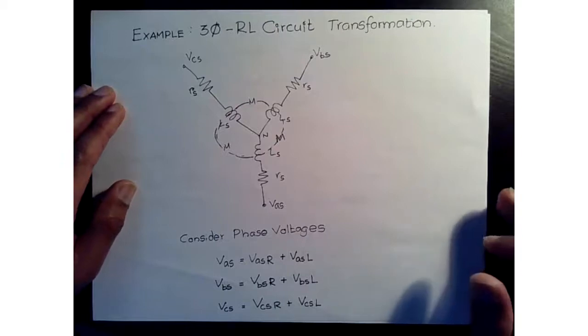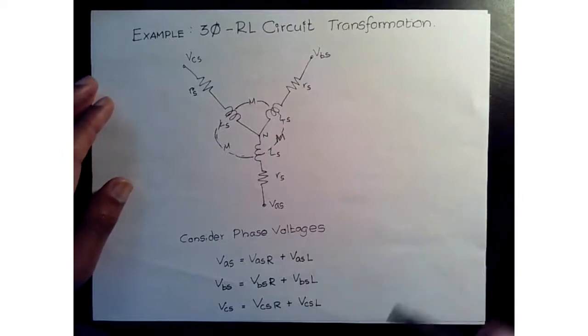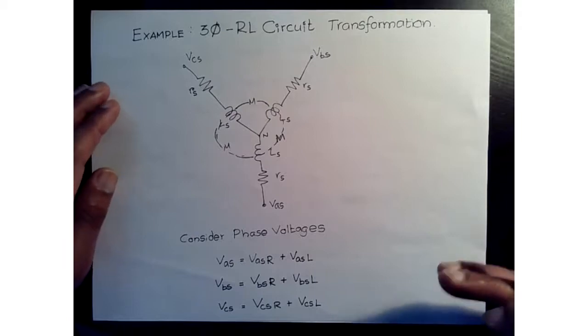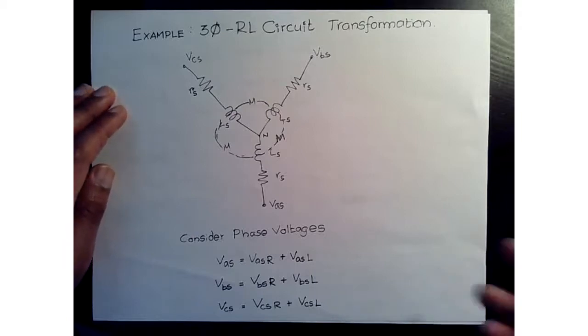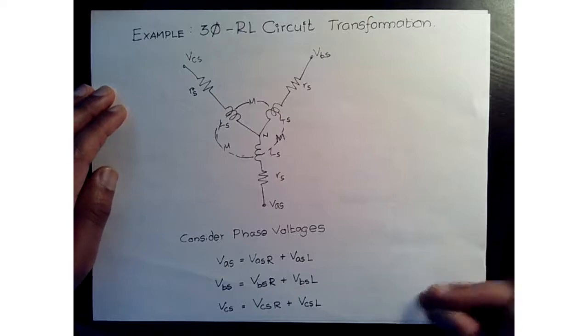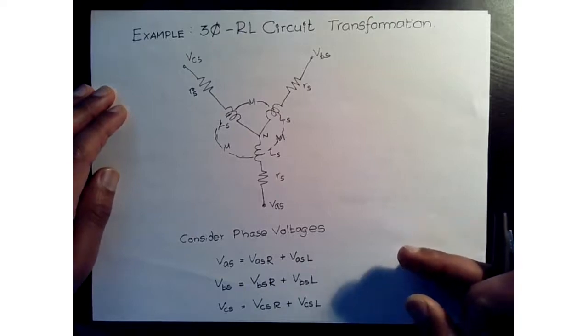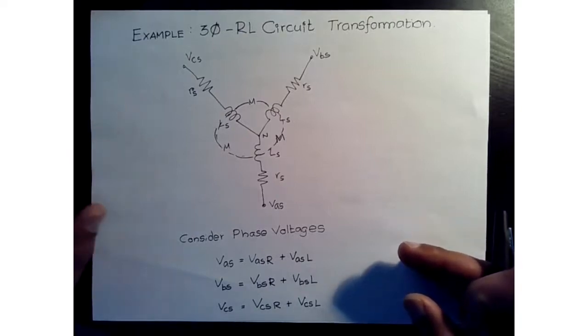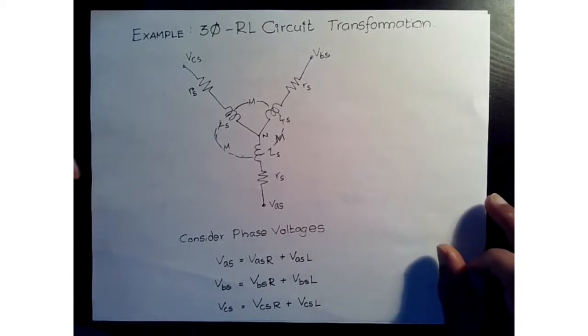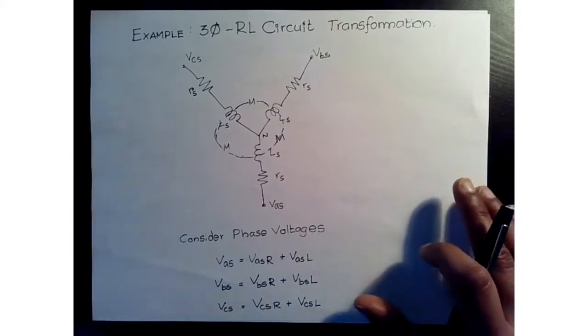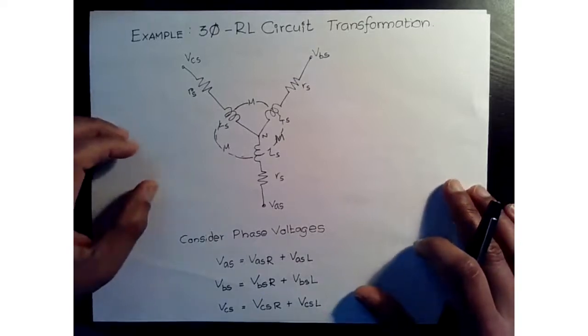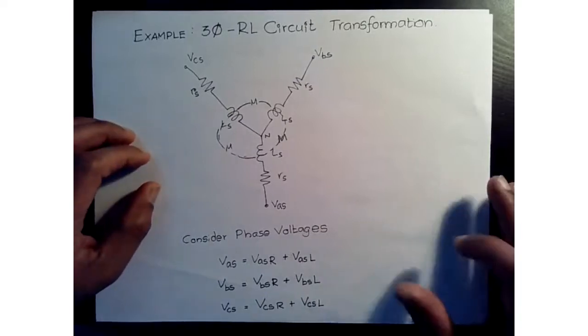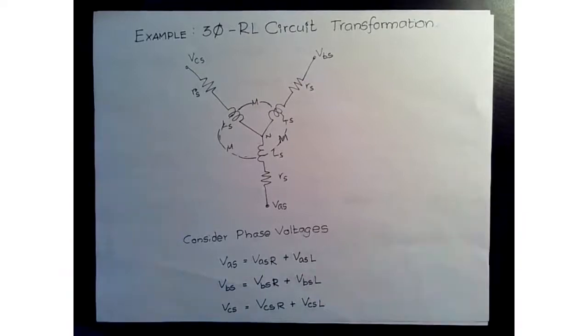The rotor frame, or rotor reference frame, implies that your frame is moving at the same frequency as the rotor of the motor. That helps us study the rotor variables. Depending on the type of motor, sometimes the rotor frequency is related to the synchronous frequency, which makes the machine simpler for analysis. So we've been talking about that.